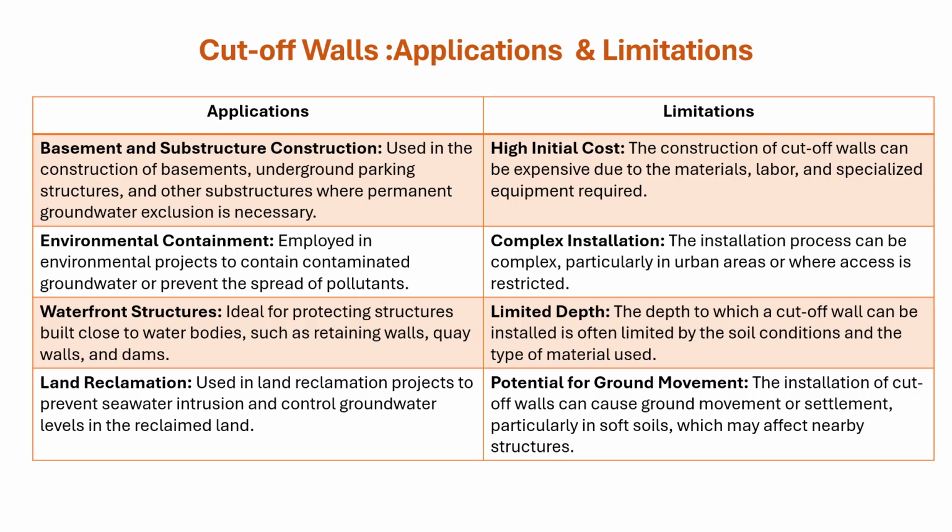What are the limitations or disadvantages? The high initial cost, the complex installation, it's not suitable for any depth, only for limited depth, and when using cut-off walls as the dewatering system, please keep in mind that there's a potential for ground movement, such as settlement, mainly if we are using the system in soft soils.